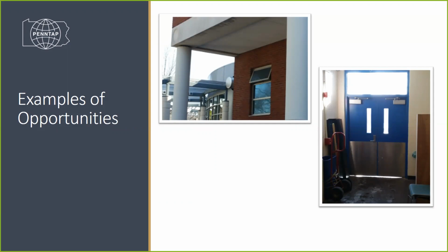So now leading to that, it wasn't a building envelope issue after all. It was more of a heating issue. And the bottom left photo reveals a lot of air infiltration. If you look, you can see a lot of natural daylight under the doorway there. So you have a lot of airflow coming in. When you do the measurement of the actual airflow coming through those doors, that actually measures to the size of about an 8 by 11 size piece of paper. So imagine having a hole the size of that in the middle of that door. That's a lot of airflow.